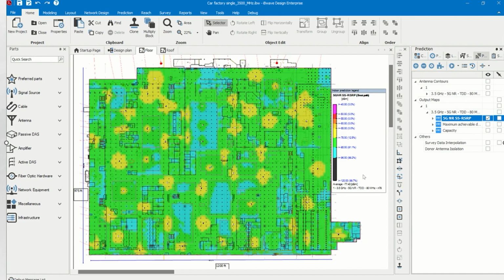In practical terms, what you would want to do is to identify the areas where the sensors will be and focus on those areas to have negative 96 dBm or higher there. Here I assumed the uniform distribution and I targeted 100%. It is really not realistic unless sensors are really everywhere in the factory, which they probably aren't. So this shows my coverage heat map.